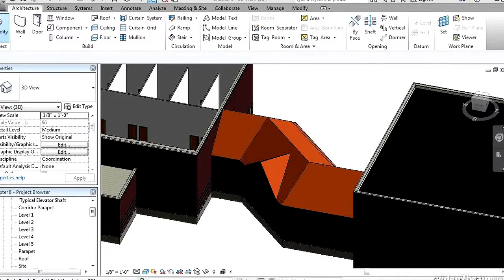The deal is we need to actually edit the footprint of the roof. Then we need to split the area of the roof that has become the dormer. We add a couple of slope barriers and we have a dormer. But actually, the first thing we're going to have to do to fix is the third floor floor plan and introduce a new topic called view range. As you can see, we have a dormer in here.